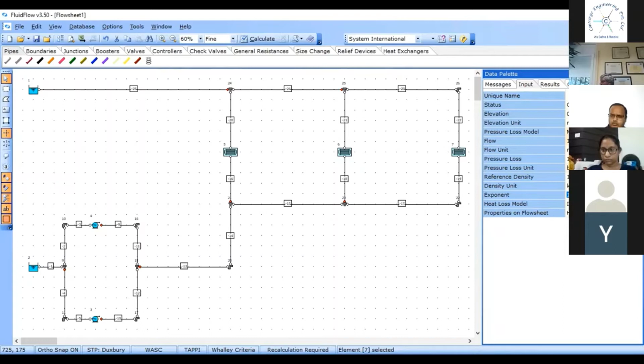Then the third option is fixed value. Fixed value means whatever may be the flow rate, pressure drop is going to be, let's say, 1 bar. This is not really a correct way of doing it, but still, in order to keep things simple, we can consider this. So flow rate is 100 meter cube per hour, then also delta P is 1 bar. Flow rate is say 90 meter cube, then also delta P is 1 bar.